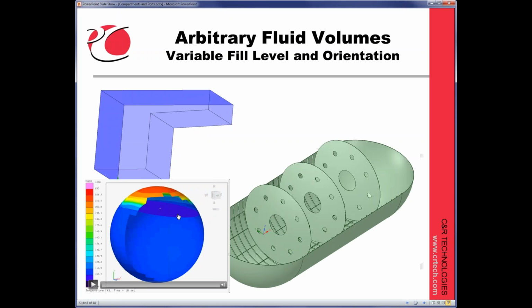This oval, if you look here, is actually the liquid surface. And what you're going to see as we're executing this is it draining. But not only is it draining, but we're rocking back and forth. This was intended to be like an LNG tank on a ship or a train. And you can see the motion as it slowly drains from the bottom here and the wall warming up during the event.